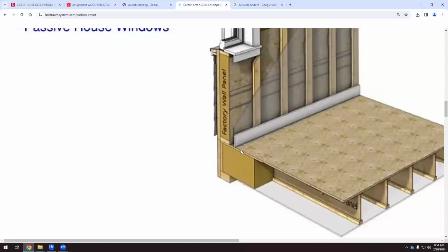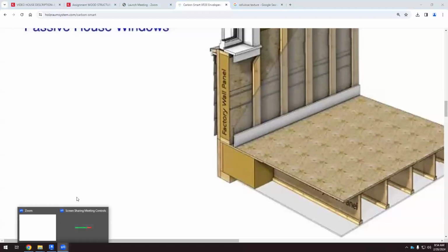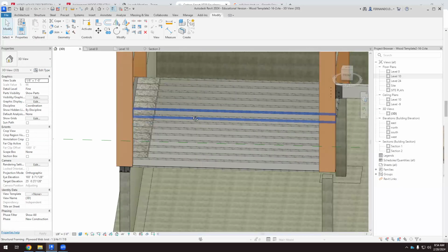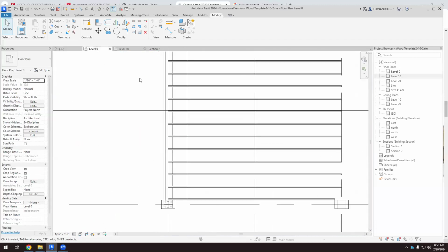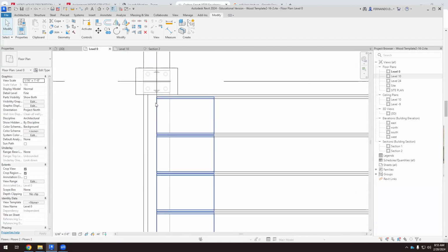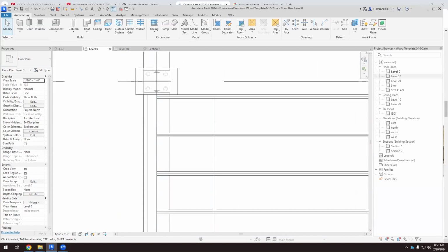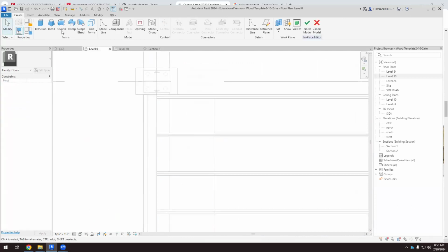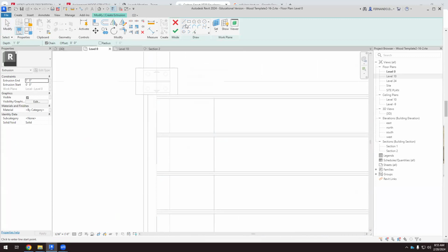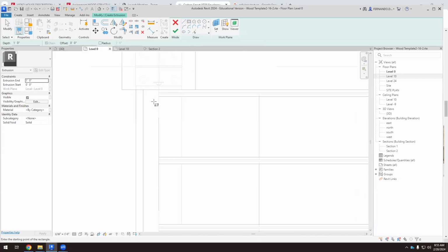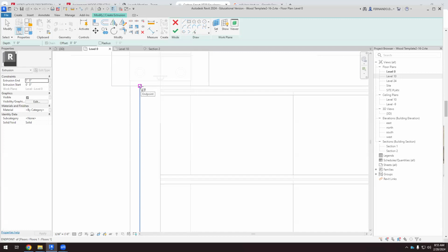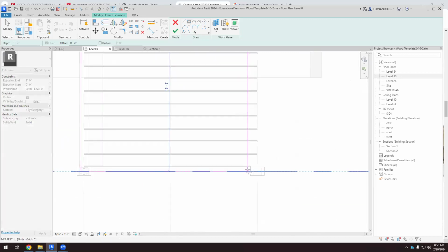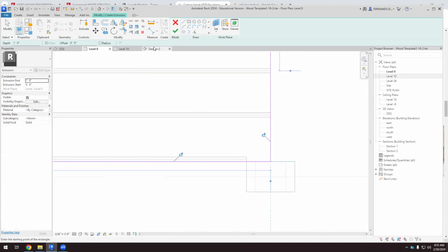So what I'm going to do is place the board on this floor. If I go to level 0, I'm going to select architecture. I can select a floor, but I think a component model in place will work better. That's a floor, of course. And if I use extrusion, I can start here, and then I can finish, let's say, there.